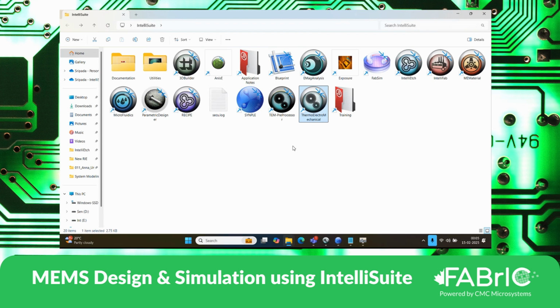The challenge of using 3D Builder when we have multi-layer geometry can be difficult in the beginning. It's not that we cannot use 3D Builder at all for multi-layer devices; we just have to abide by the rules of FEM, the finite element method. The first rule is that we need to have the mesh lines or common node points aligned for the geometry to have a proper mesh. In such scenarios, we may spend a lot of time designing them.